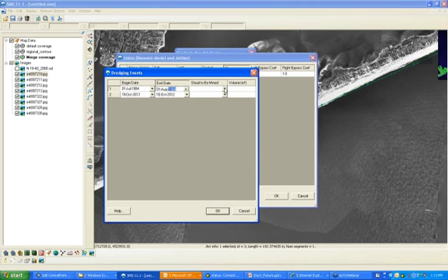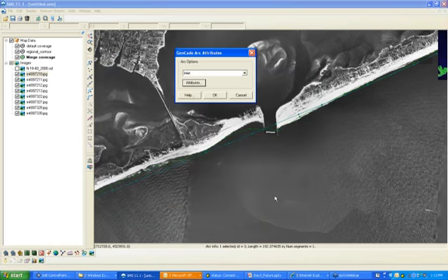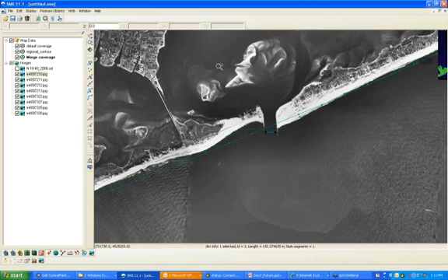We're going to click on the shoal to be mined, and I'm going to click ebb, and then I'm going to enter my volume, 134,562, and we'll click OK, and OK again. There are additional dredging events for this case, but I'm just going to ignore those for now since we've already done dredging since we did that yesterday. And I'll click OK.